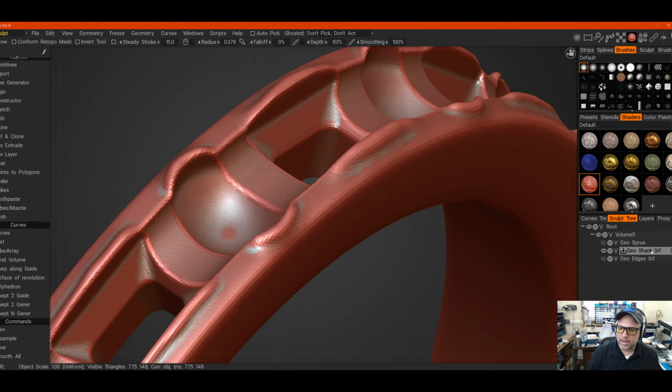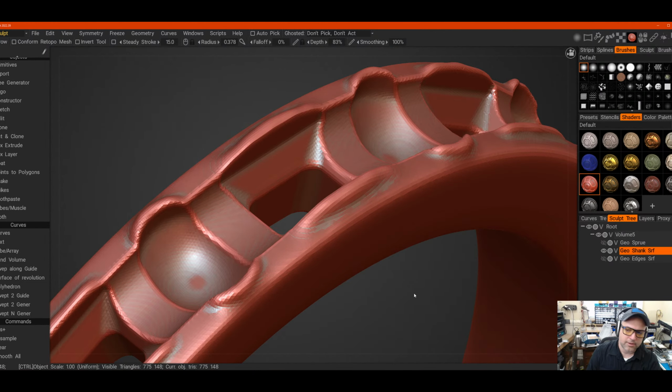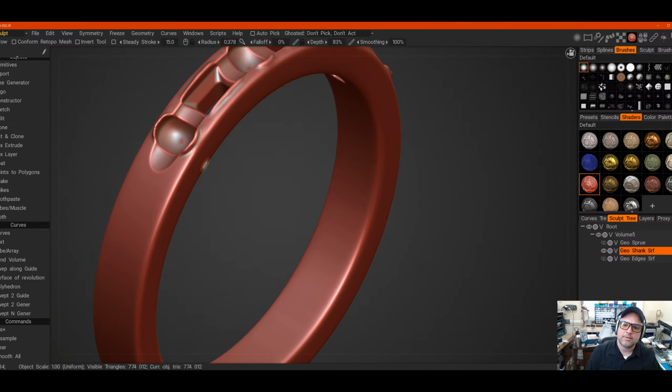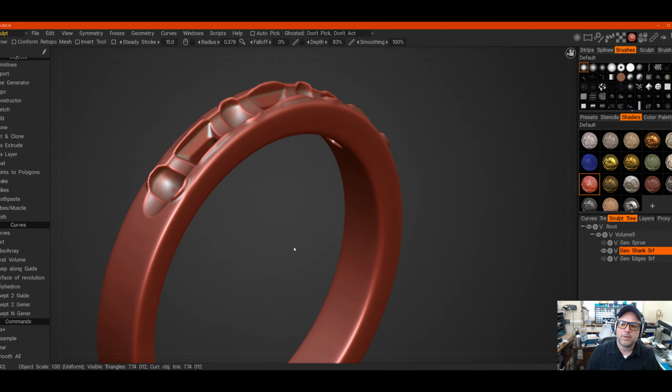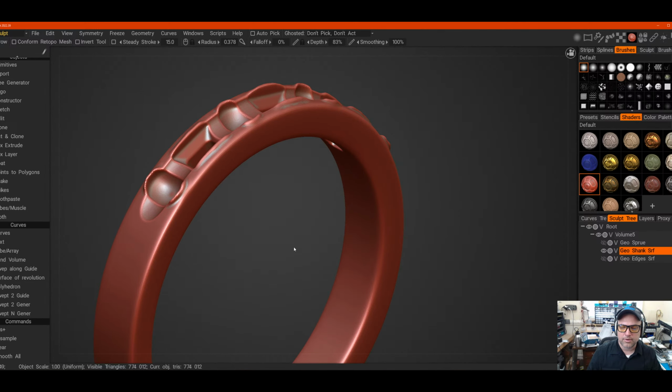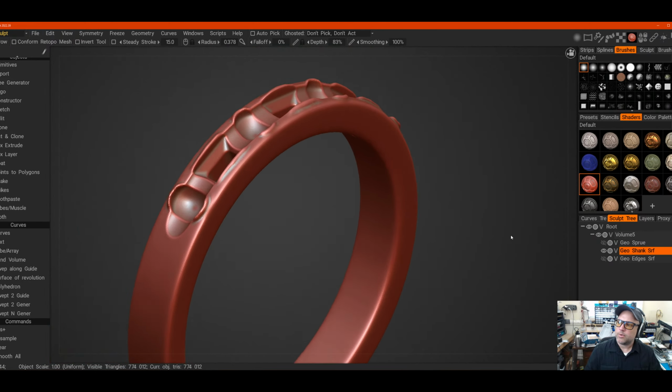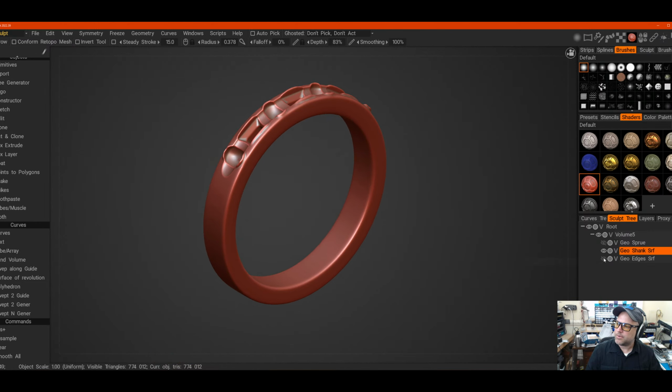So I undid back to where we're at the 1 scale, and I'm just going to hit Control R a couple of times. I always kind of do that, because when I'm in Rhino, I'm not looking to make sure that it's actually curvature continuous. I strive for it. I don't obsess over it, because a couple of Control R's, and then by the time it hits the buffing wheel, it'll be continuous. So if it's pretty much continuous, it will be actually continuous by the time we get to the finished piece.